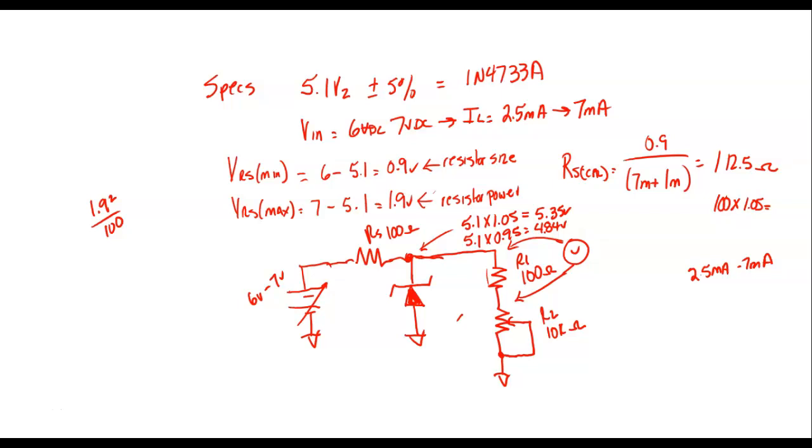That's the tolerance range. Remember in DC what y'all had to do, you say, okay, I got a 100 ohm plus or minus 5%. And what y'all did was take the 100 ohms and probably multiply it by 0.05, and you came up with a number. Then you subtracted that number, and then added that number to find out if the resistor, once you measured it, was in tolerance or out of tolerance, right?